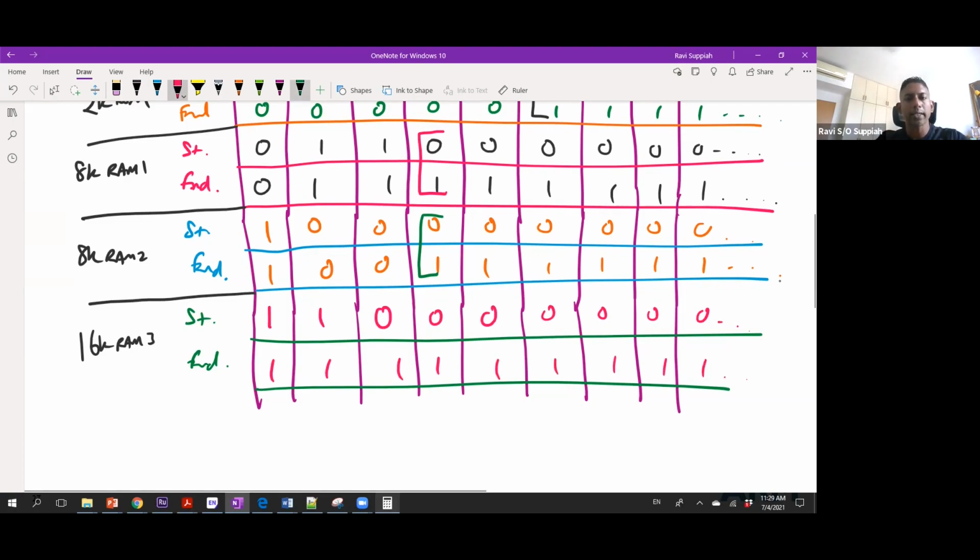So in this you can see that only the upper two bits are constant. The lower bits are all changing. All right, so the whole idea is we want to look at bits that are constant while I'm performing this memory access, because if they're constant, that means by just looking at these bits I can activate the device that I'm supposed to talk to. All right, so that is the thinking.